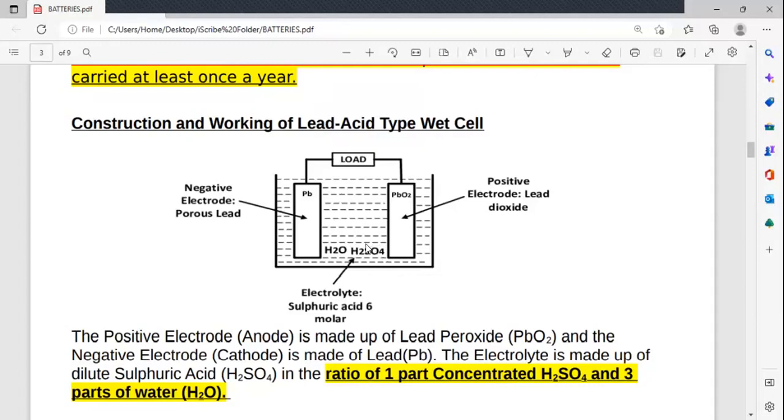And then we saw during discharge that your already diluted H2SO4 is going to get further diluted by the addition of water due to that chemical reaction. So that is why our voltage and specific gravity are falling during discharge. And then when you're going to recharge it, we saw that the voltage increases as well as the specific gravity increases, for the simple reason that voltage increases because both the original electrodes are got back. Also, H2SO4 is created due to that chemical reaction.